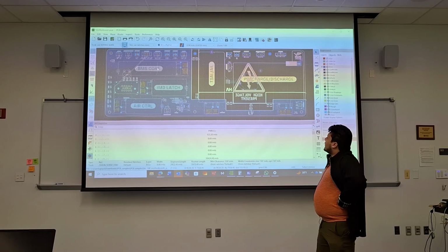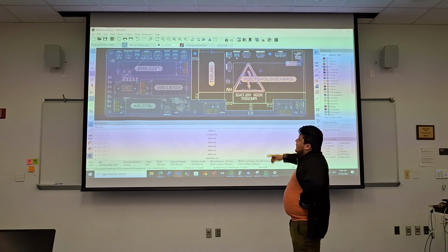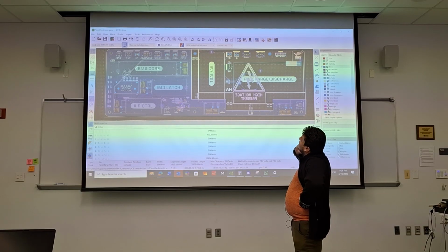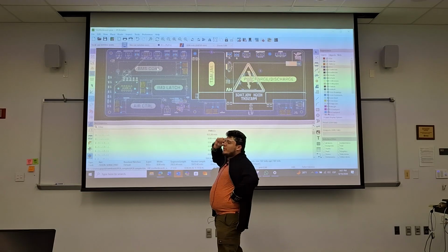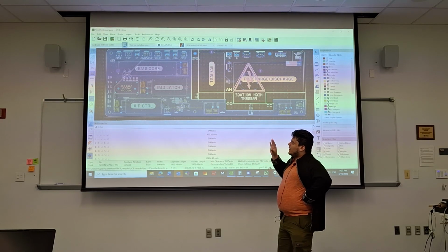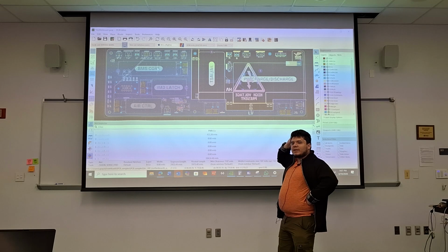I'm not sure. It'd be good to get a bunch of eyes on it before taking any drastic decisions, but I will say having such long runs of ungrounded or unshielded traces and sense lines, not great, but not the end of the world. Because I do see that here you also connect to a bunch of other cards. And so if those are also not correctly grounded, have you all looked at the grounding scheme? I'm not an expert in necessarily these systems, but I see they all go to the same ground, but is there a chassis ground that this is all supposed to be connected to?